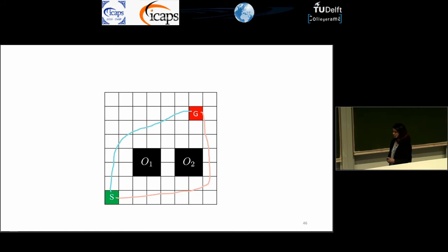So you said that this homotopy class may not be applicable for trajectory optimization. Are you familiar with the work, I'm not sure of the name, on trajectory optimization by a person at MIT, which was actually exactly for a humanoid robot, where he discretized the environment based on convex obstacle-free discretization of the environment, and then it becomes a subclass of trajectory optimization.